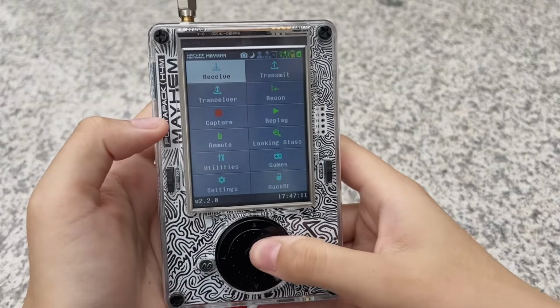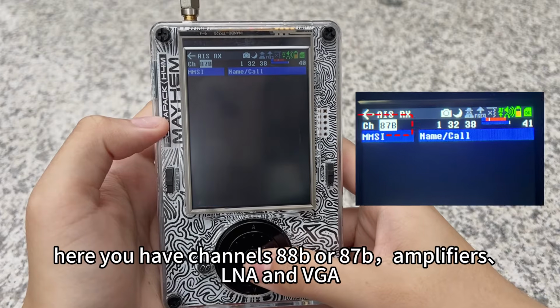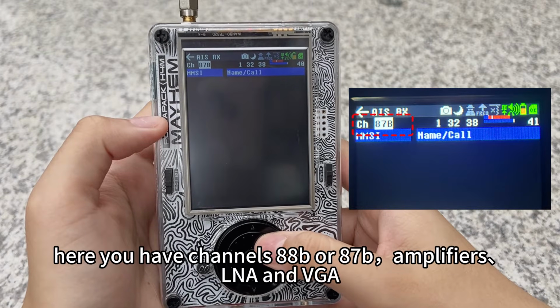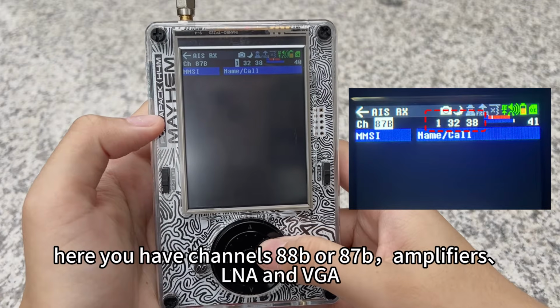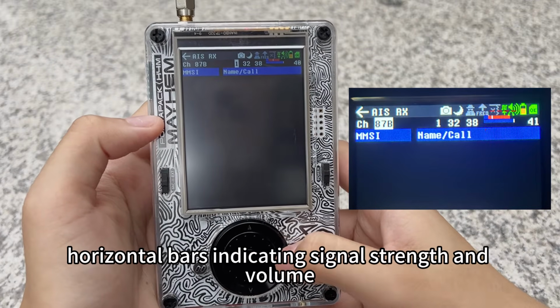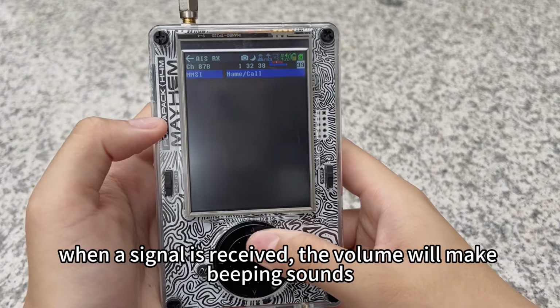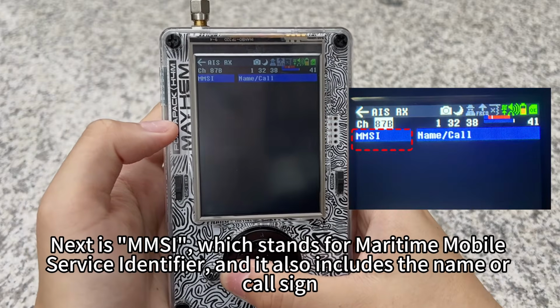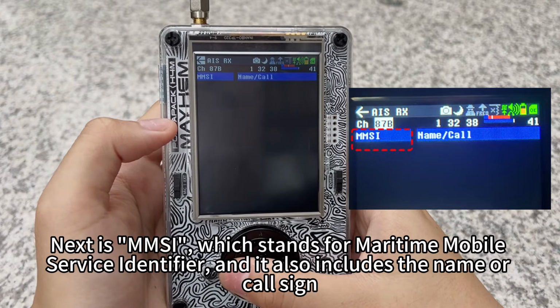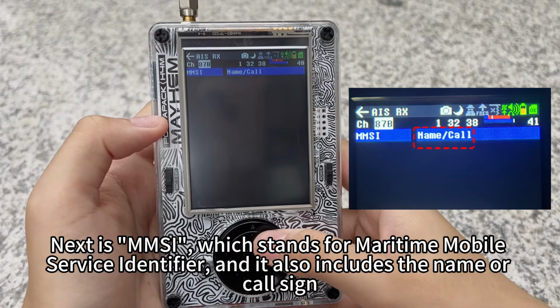AISboats. In AISboats, here you have channels 88B or 87B, amplifiers LNA and VGA, and horizontal bars indicating signal strength and volume. When a signal is received, the volume will make beeping sounds. Next is MMSI, which stands for Maritime Mobile Service Identifier, and it also includes the name or call sign.